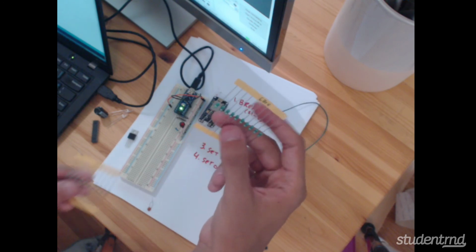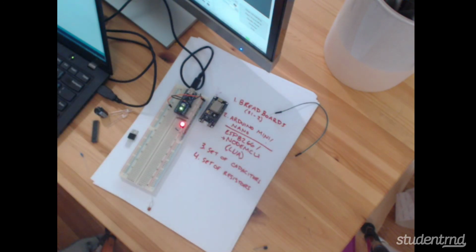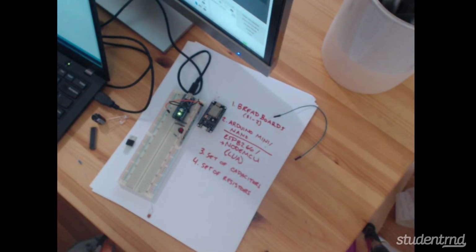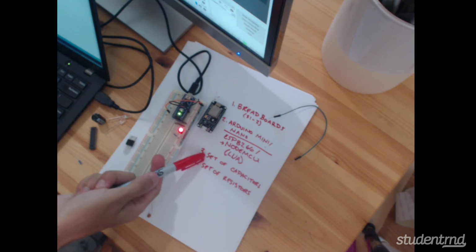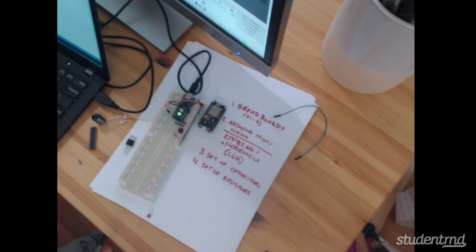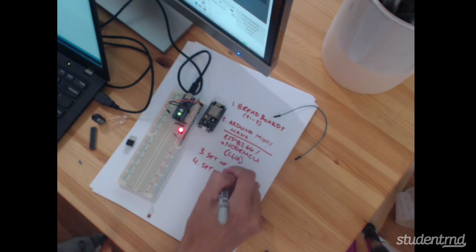And you'll get a bunch of these in a bunch of different values, because you'll need a lot of different values in resistors. For something like an LED, like I said, we probably wanted, I think we said 62 or 82 ohms. For certain things, like what's called a pull-up or pull-down resistor that you'll use for transistors, those will be more like 1,000 ohms or a kilo ohm or more. So I'd recommend getting a set of resistors and again a set of capacitors. Capacitors are less important. You'll probably use resistors a lot more. And again, both of these are probably like $5.